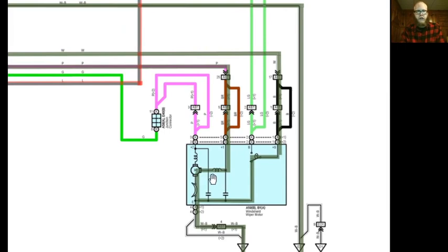I've got a couple different brushes. This would be considered a shunt motor, but it's talked about inside the video for how a DC motor works. And you can see I've got 3 different brushes. I've got one dedicated ground brush. This is always going to be ground. But then I've got this brush off at a 90-degree angle and a brush opposite at 180 degrees. This is my low speed. You see how the brush isn't lined up in the way that we could get the motor to spin the fastest possible. This is my high speed.